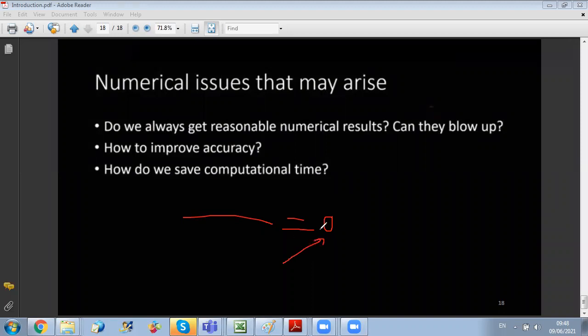As you do iterations, the residual is the number after the equal sign. So instead of 0, you might have 10 minus 4, 10 minus 5. You will select a certain criterion to stop. You will say, when I reach residuals of 10 minus 5, for example, I will stop iterations.